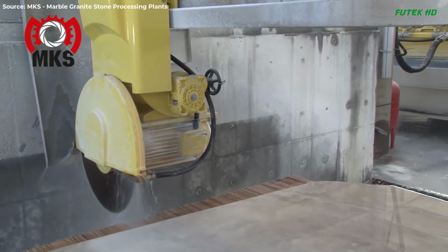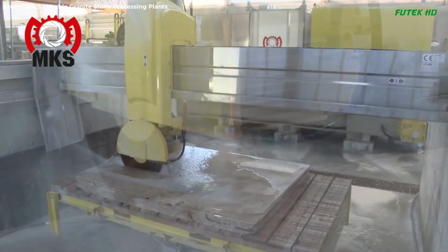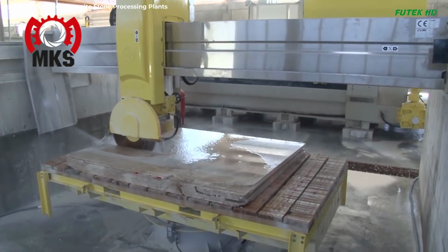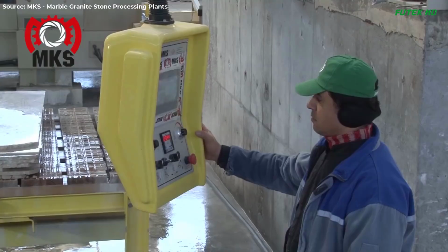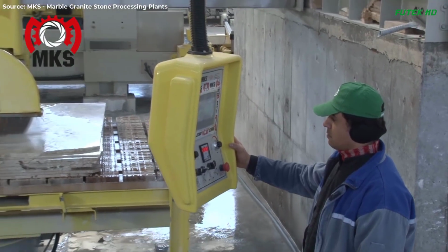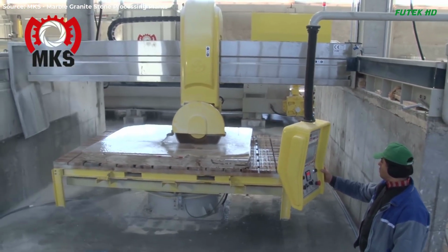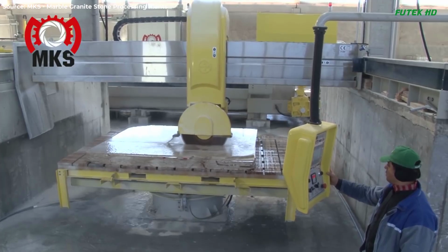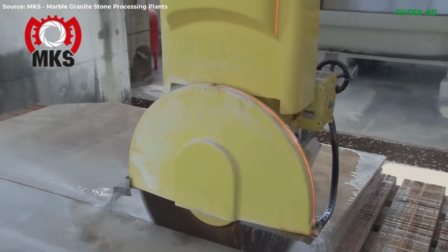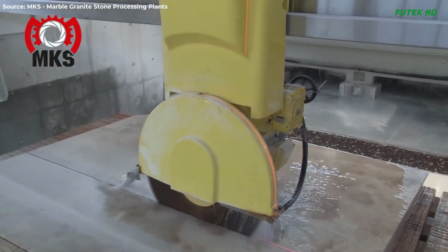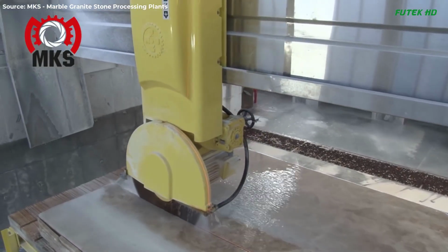The main shaft, made from forged steel and tested for cracks and porosity, is a robust component of the machine. It undergoes hardness and material analysis after heat treatment to ensure durability. The shaft's movement is transferred to the blade rack through a system of connection rods and a flywheel. This assembly is engineered to balance dynamic forces, ensuring the longevity and stability of the machine.